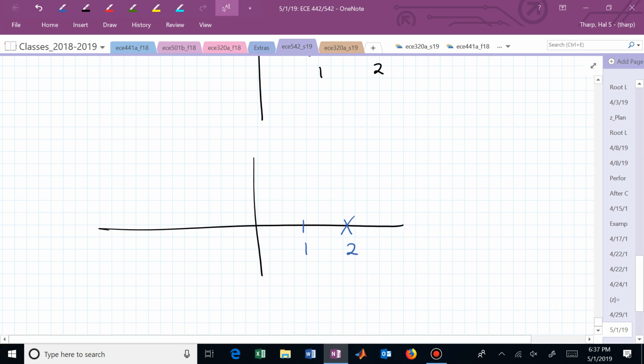Well, do you remember if the zero was sitting maybe here, how we controlled that one? Now we're in our restaurant again, aren't we? Two poles walk into a restaurant with a zero on their left. Remember? So now our controller would say, I can put that there, and these two are going to be coming together. How many branches do I have of my root locus? I have 2 because I have 2 poles.